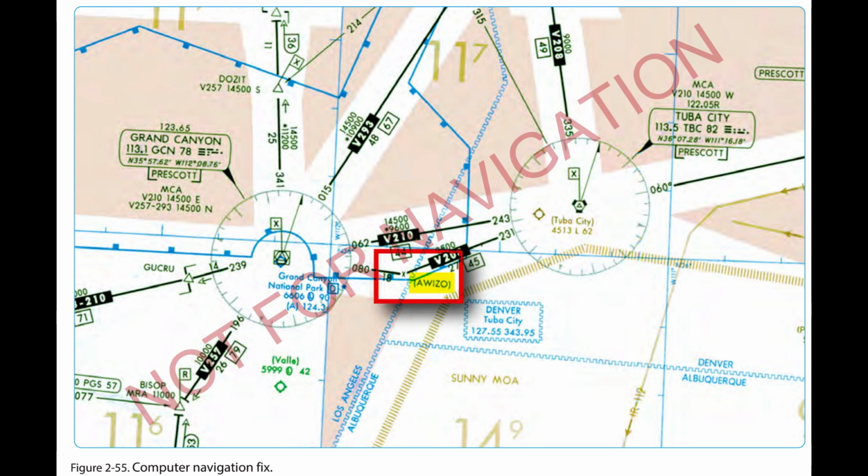These points appear in the list of waypoints in the approach procedure database, but may not appear on the approach chart. A point used for the purpose of defining the navigation track for an airborne computer system, i.e. GPS or FMS, is called a Computer Navigation Fix, CNF. CNFs include unnamed DME fixes, beginning and ending points of DME arcs, and sensor final approach fixes, FAFs, on some GPS overlay approaches. To aid in the approach chart/database correlation process, the FAA has begun a program to assign 5-letter names to CNFs and to chart CNFs on various National Oceanic Service aeronautical products.